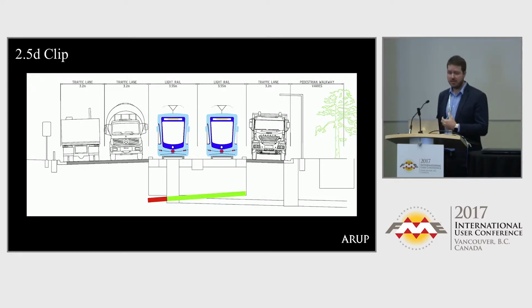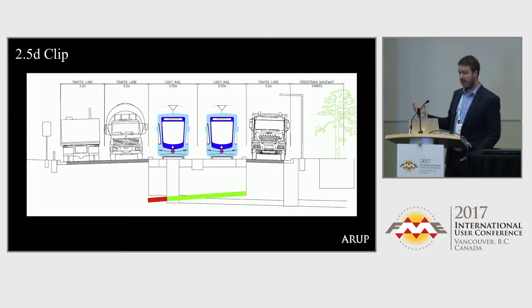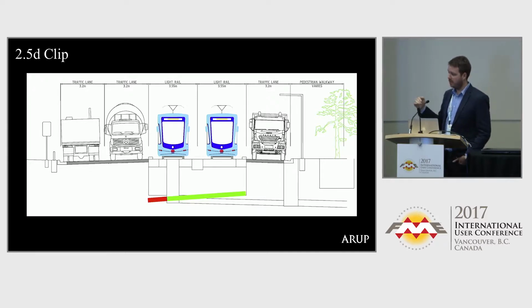If the start or the end elevation was within that track slab, there would be, I've got the colours the wrong way around, I suppose. Green would be a pass, so that would actually be a clash, and red would be a fail. So that would be a hard classification. You'd use the inverts and the obvert levels. If there wasn't an existing obvert, we would use the pipe size to offset that value back up. For AS5488, there is a horizontal and a vertical tolerance. So say if this was classification D, we would add another 1.5 metres onto that to pull it up to make sure that we had a clash, to cover ourselves.